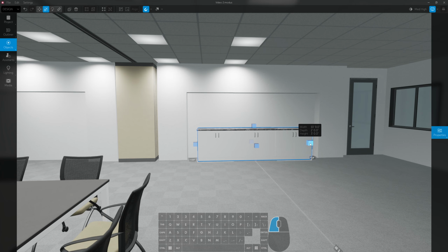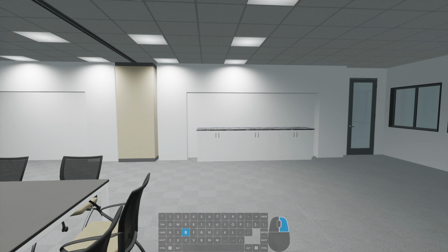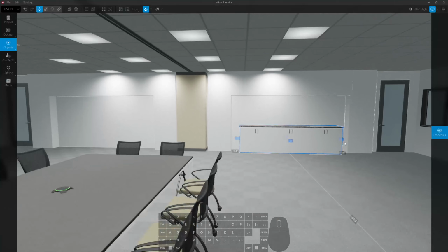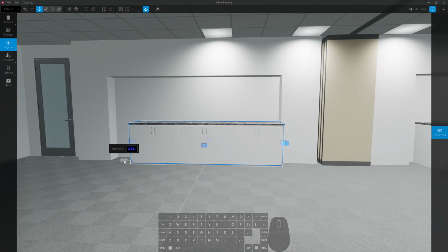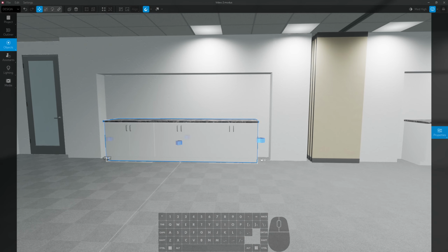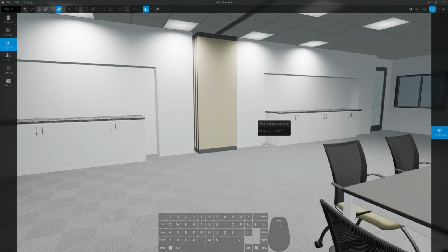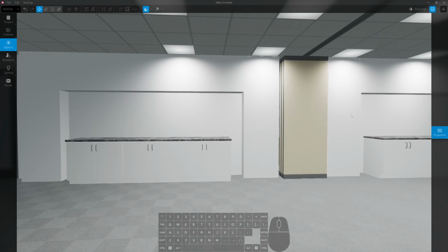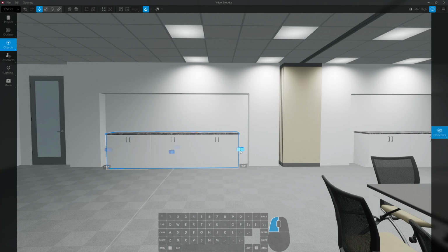And just about 1 foot. Oh, perfectly 1 foot of space on that side. Now, if I didn't know the measurements of what I was looking to do here, oh, see, we've got 1.05 here. I could check the measurement here. See that it's 12 feet, 10.9 inches. Maybe this one's slightly different, 10.3 inches. Yep. So I could either adjust these walls and where I have everything placed, or I could adjust my cabinet here and just get it close enough.